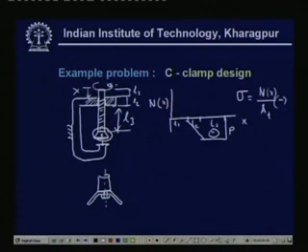Then of course, we have the torque. Let me draw the torque distribution. Now, here up to this point there will be only the torque which is to overcome the collar friction here, that is, as we have mentioned before, there will be friction. So, we want to overcome this friction, and that remains constant here.